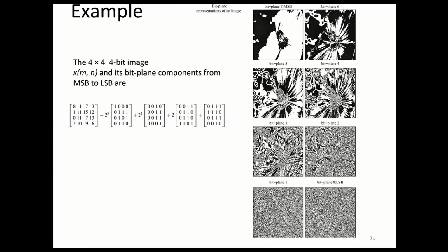Yes or no? And this is one of the methods for compression as well, where we discard some of the low bit planes and just start with this. In this way, I can store a smaller number of bits, so it's a compression. Although I will lose some information for sure. So that's why we call it least significant and most significant in terms of image. This is a real example of the image, and this is just a number, so they are not mapping each other.